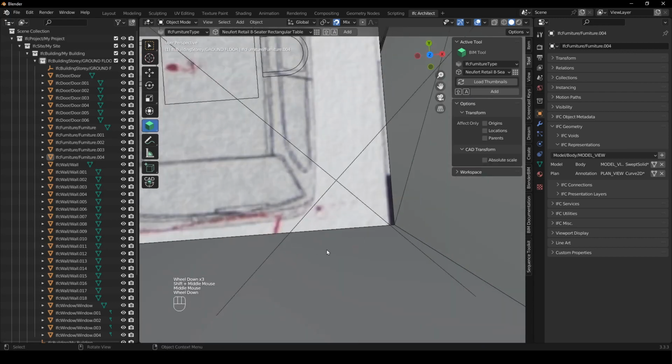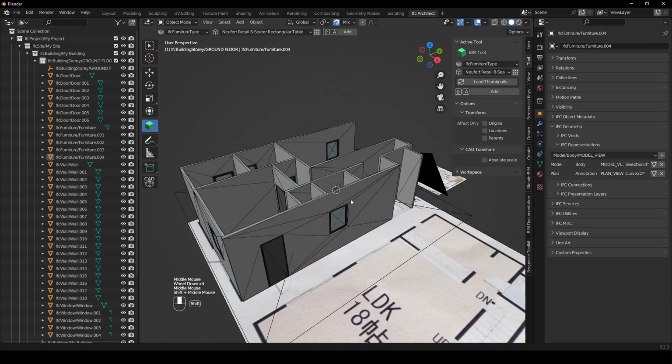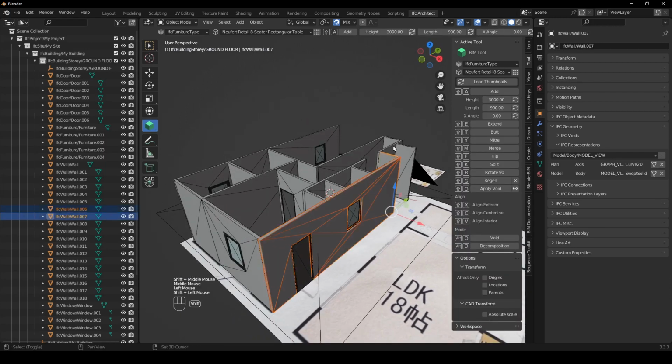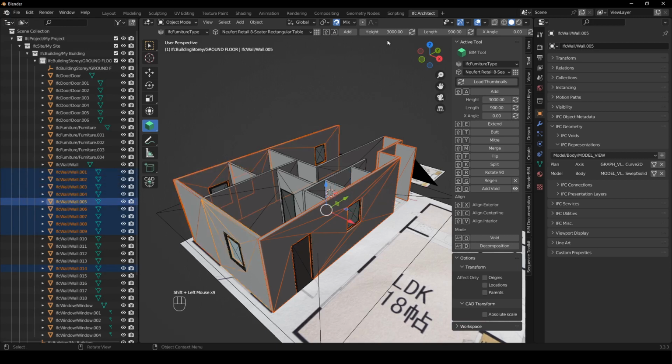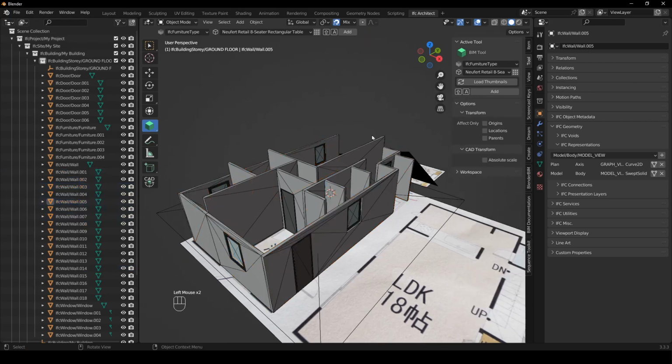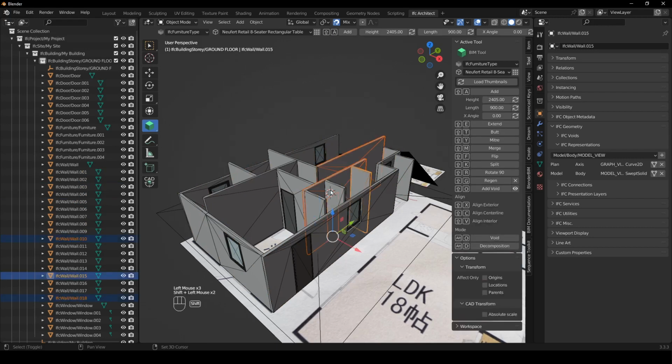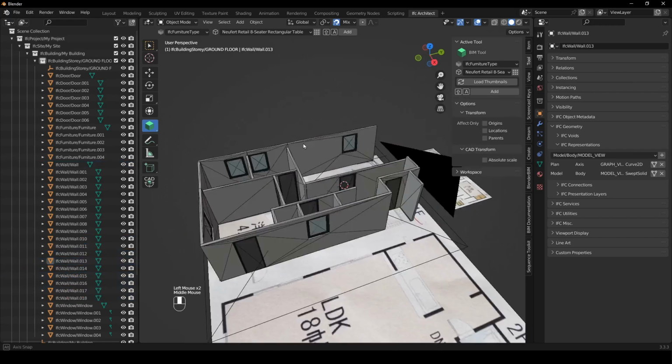So what we've got to do is go into the 3D view, and we're going to change all the outside walls' height to 2.4 meters. So we just go here to height and we say 2405, and we refresh that, and they've changed. And then we take the internals, and all of these become the same height minus 200 for the slab. So 2205, and there's the height.